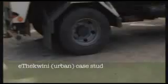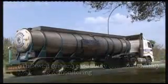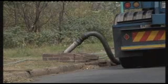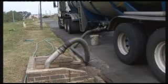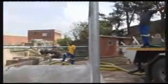Also, when we get an alarm of an overflow event, then we put in place whatever mitigation measures are required, either throttling that flow of sewage, or diverting it if there's a possibility upstream, and also disinfecting before it gets to the receiving waters.